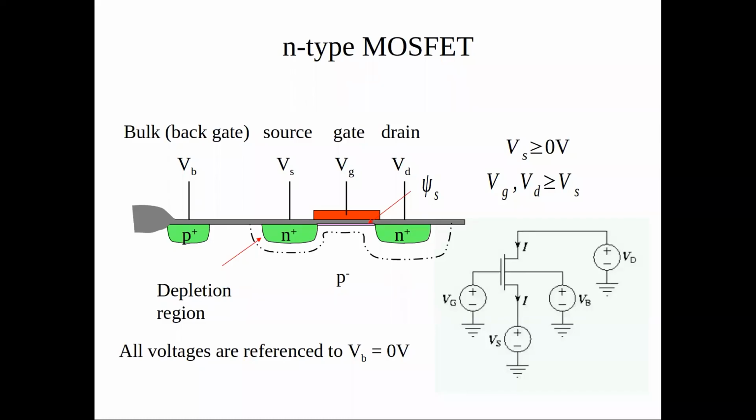The other thing that's denoted here is this double dot dash line. So this is denoting the depletion region. Remember, we have p-n junctions, and when we put together a p material with an n material, there is a depletion region that's there. Depending on the difference in concentrations and so on, you can think of it as thicker or thinner. So it's important to remember that there's this depletion region also in NFETs because it's made of p-n junctions.